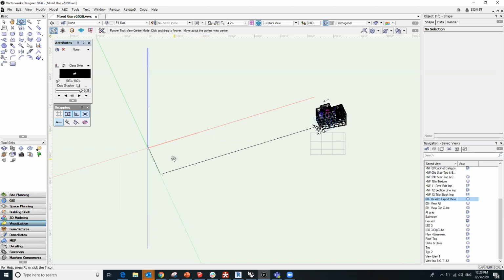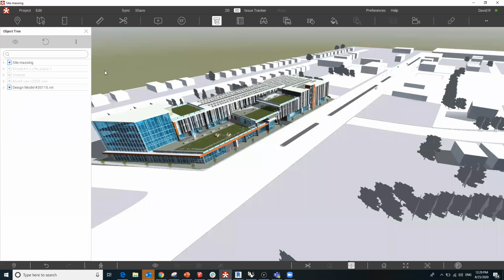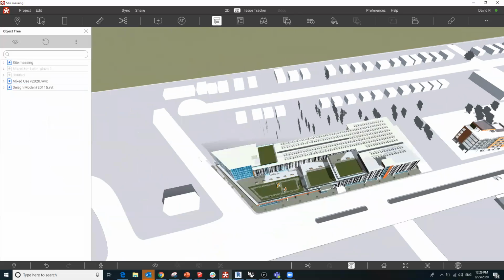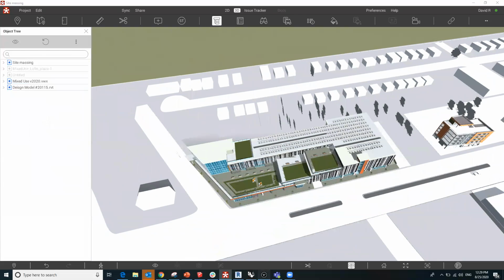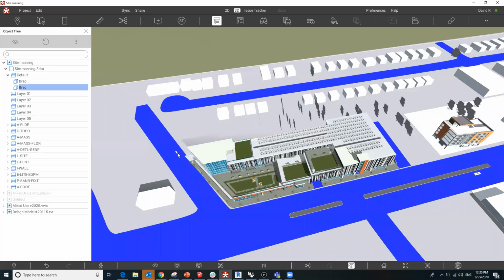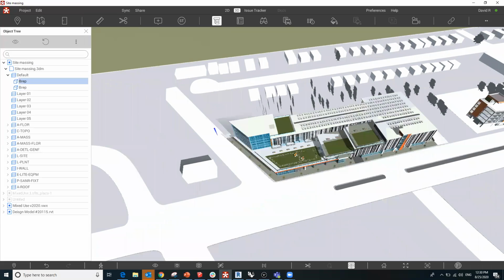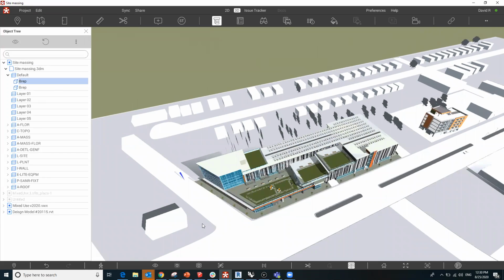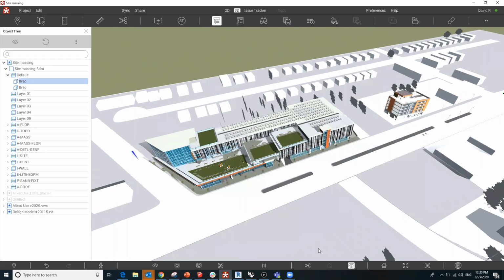So again, I'll take a look in Revizto and just verify that came in correct. So I'll go to my object tool here and unhide my model. And again, just on visual inspection, if I go to Vectorworks, I want to make sure I drop the model in on this point from these two distances. And in Revizto, again, using my object as a reference point of the cone I brought in from Rhino, I wanted to come this way and this way, a certain distance, and looks like it came in really nice.